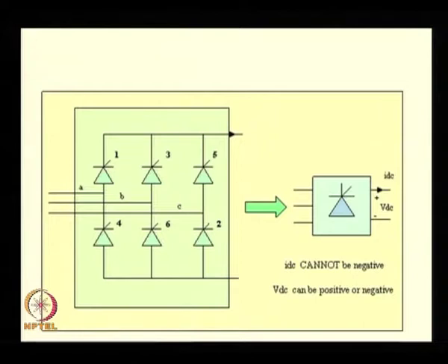In that case, the DC voltage VDC will have the 6th harmonic. It is a DC voltage with 6th harmonic, and a DC component itself. So, you have got a DC, 6th harmonic, 12th harmonic and so on. No lower order harmonics are present other than of course the DC component itself. So, you have got the DC component, 6th, 12th and so on. This is often called a 6 pulse thyristor bridge.